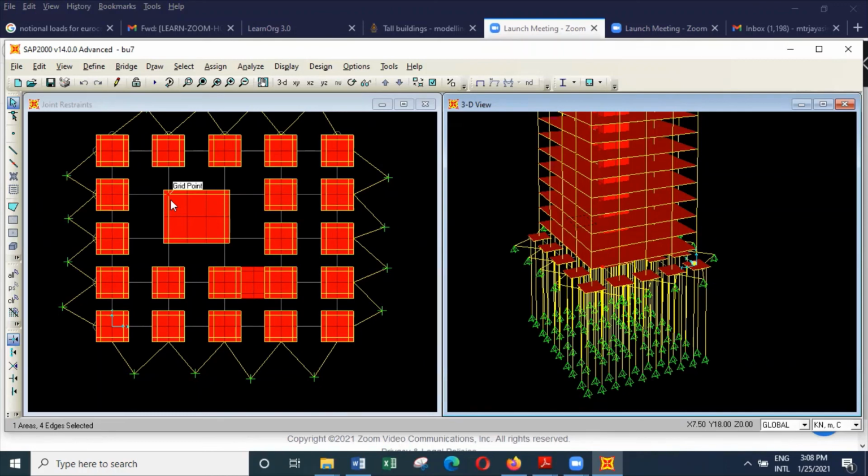Say when you use something like 1.2 meter piles, then the center to center distance with 3 times diameters is 3.6 meters. Then what is the clear spacing between 2 piles? The clear space in between two piles will be 2.4 meters.